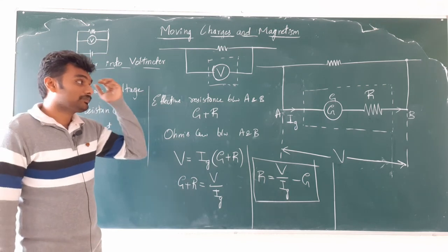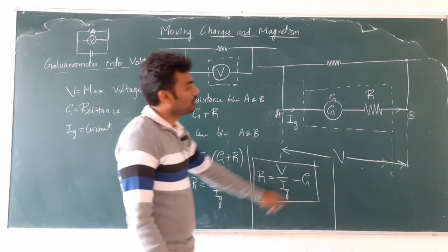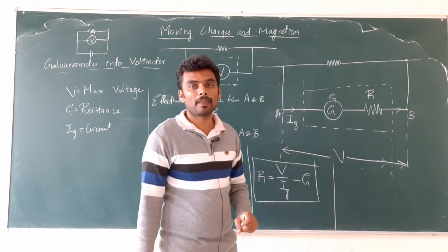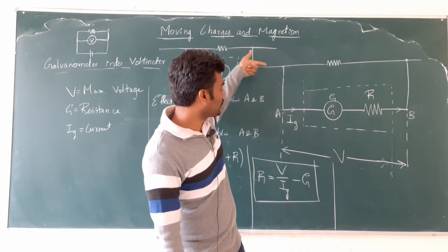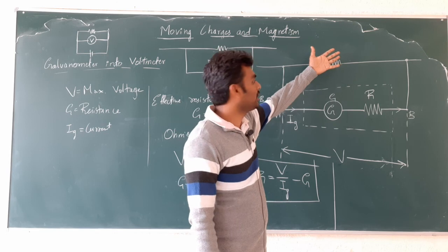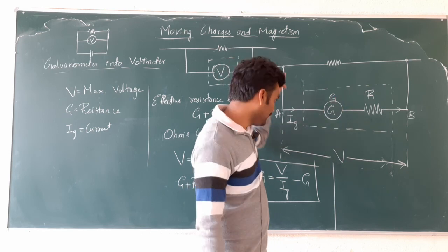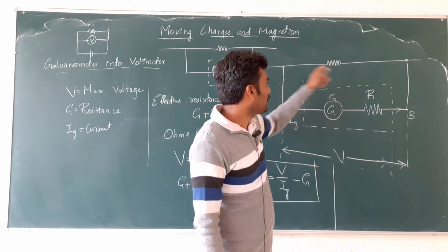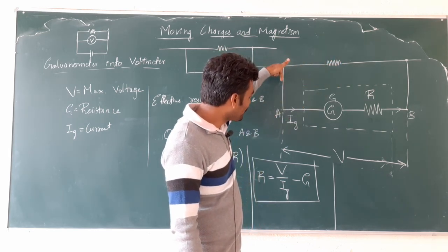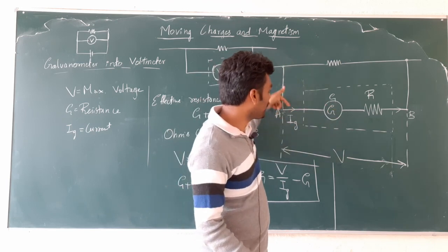And now coming to the case of the ideal voltmeter. What resistance should be connected here to make this voltmeter an ideal voltmeter? See, there will be certain current flowing in the main current through this resistor, the external part of the voltmeter. This is outside the voltmeter. Now, if I take too much current into this part, into the voltmeter, this will not be fed with the proper amount of current. So I need as little current as possible flowing through this branch of the circuit.